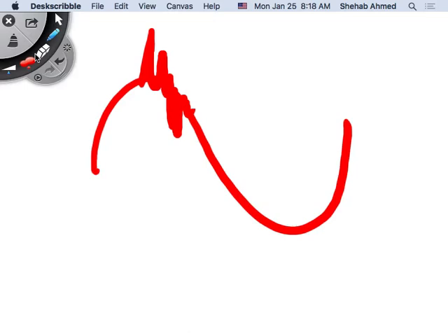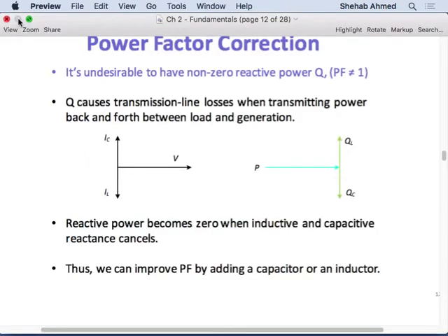So harmonic resonance is an issue that people in power systems deal with very seriously. They want to make sure, for example, that the generator's resonant frequency does not equal any of the harmonic frequencies that you're going to possibly inject into the system. So they perform a study like that. And if it does, they have to add proper filters. So this is another study that people do. We will not study that in 459, but it's something to note here.